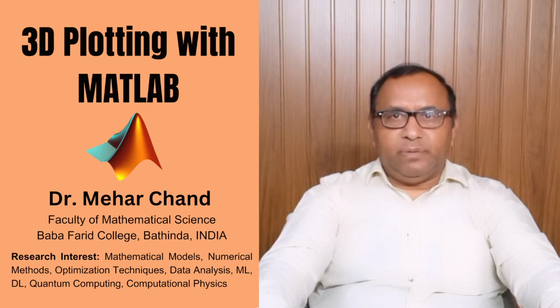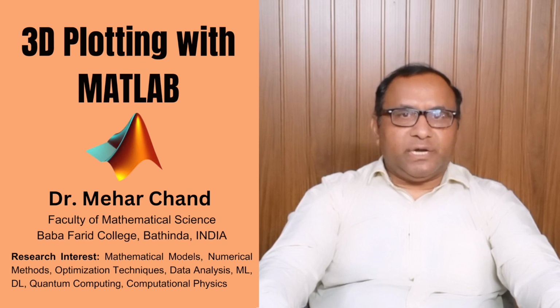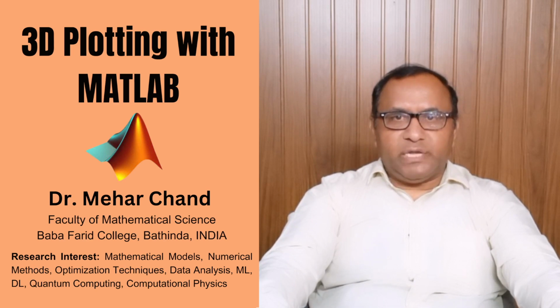Welcome to today's lecture on 3D plotting with MATLAB, where we will explore creating engaging visual representations in 3 dimensions. We will uncover the significance of visualizing data in multiple dimensions, crucial for various disciplines. This session aims to provide a deep understanding of MATLAB's tools for crafting impressive 3D plots, starting with the fundamental concepts. Through hands-on exploration with MATLAB functions like meshgrid, plot3, surf, and scatter3, you will gain practical insight into effective 3D visualization. I encourage active participation in exercises as we unlock the potential of 3D visualization using MATLAB.